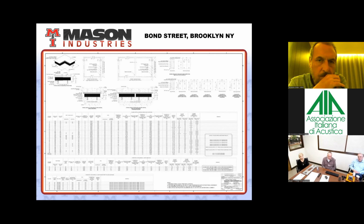The table that you can probably barely read shows loading at 80, 100, and 120% of the loads that we've been given by the structural engineer. And it shows the range of frequencies that will be achieved for building isolation near railways. It is a common natural frequency range of 6 to 8 hertz that solves the problem. And this is the result of at least 60 buildings on rubber pads near trains.